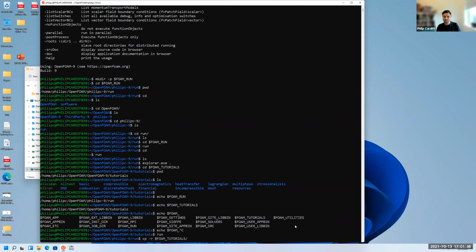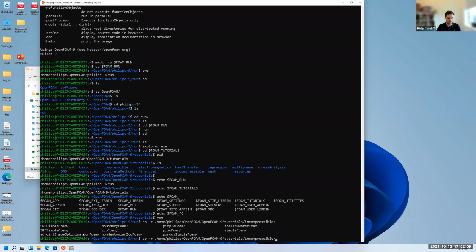If you press escape, then let go of escape, and then press Control E on the keyboard, that will replace the environment variable in line with me. So that's fine. Then I'm going to go incompressible, so INC tab, and then the way they've broken it down, if I press tab twice here, it's broken down by OpenFOAM solver.